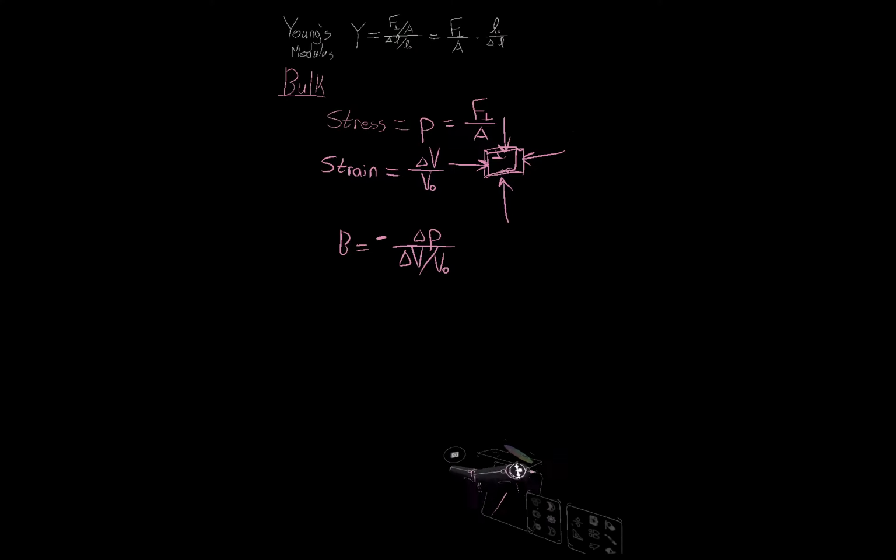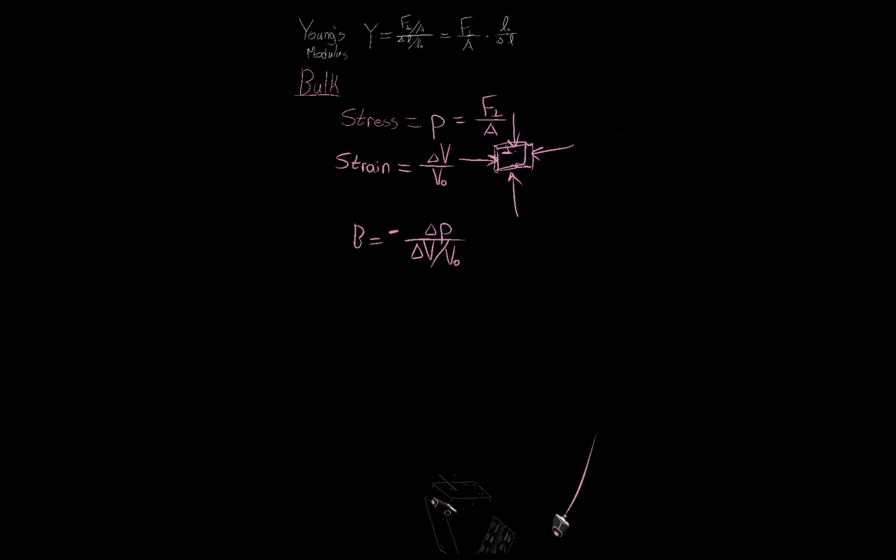So the same amount of tensile stress as bulk stress. However, concrete can withstand great compressive stress, but it can fail under relatively weaker tensile stress. So this makes it ideal for some use cases, but a horrible choice for others. You can have many pounds of force resting on it, but if you try to pull it apart, it is brittle and it pulls right apart.